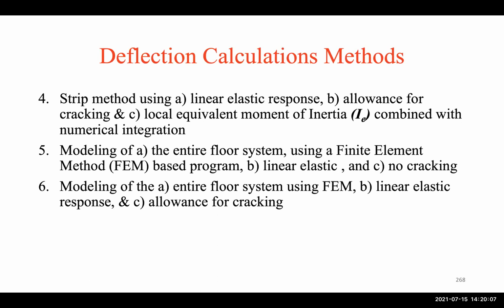And then there's modeling of the entire floor using finite element-based programs using linear elastic analysis with no cracking. We do that every day in the offices. When you design it, then we check deflection, and that deflection is based on linear elastic analysis with no cracking. Okay, now this can be modified to allow for cracking by providing a factor to the moment of inertia. For those of you who use RAM Concept, or SAFE for the design of concrete floors, that's typically what we do.